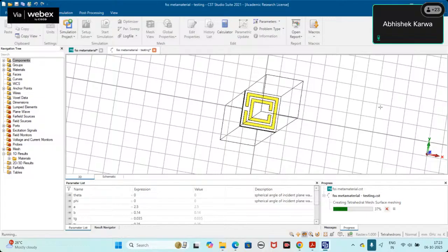That is the far field distance. That means you are placing your structure with reference to your antenna in a particular direction, with a particular formula and a particular distance. Now this D is the opening of your horn antenna, the aperture. D is the maximum opening of the antenna, the diagonal one, the maximum dimension. That is what will define it.